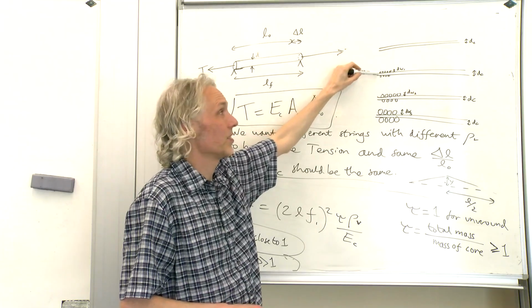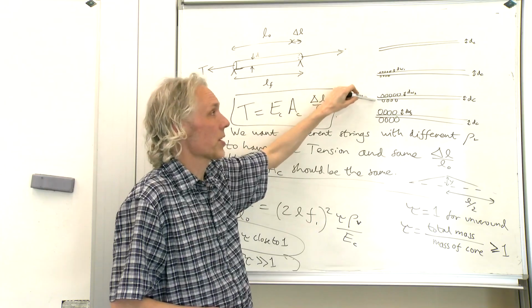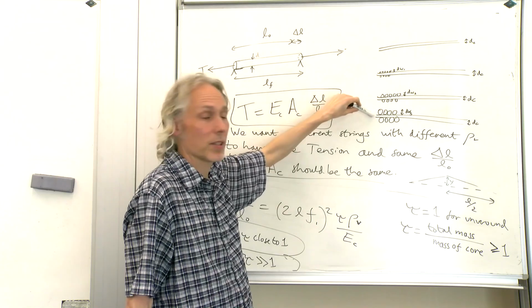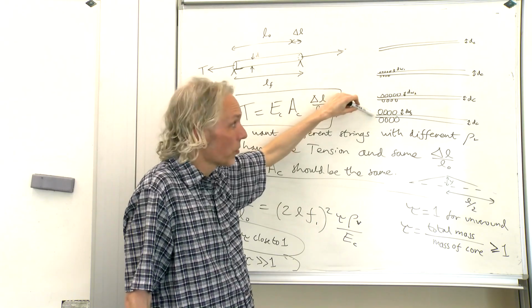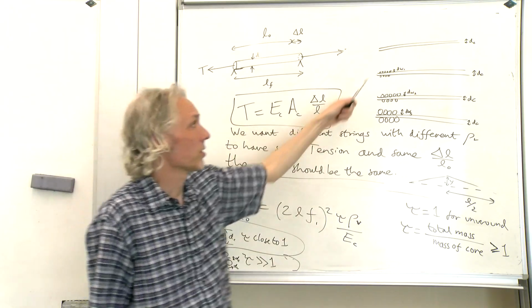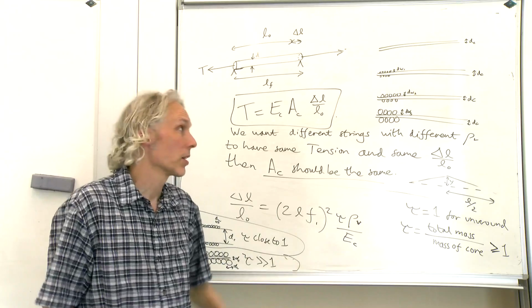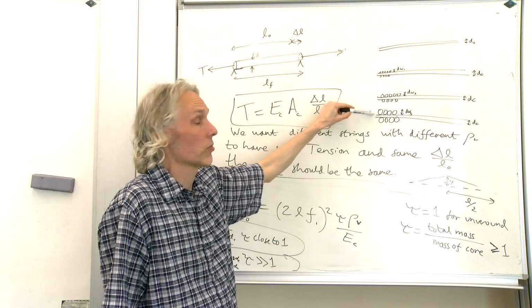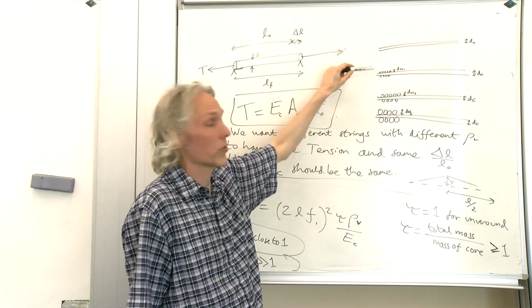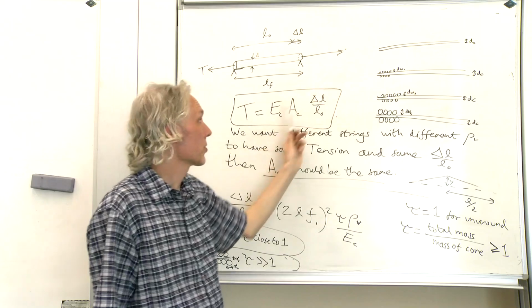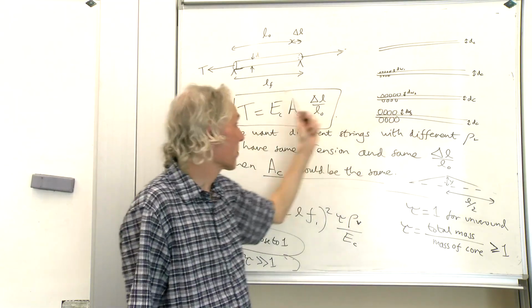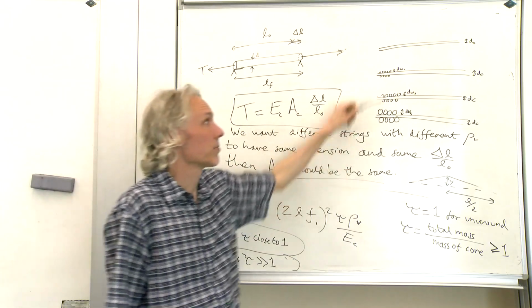And then this DC for this hex core is the same exact number as the DC, the core width for the A string, which is the same exact number as the core width for the low E string. So that means that if I design the windings right, to have thicker windings for the low E, thinner windings for the A, and finer windings for the D, we can get the tensions the same, and if you get the tensions the same and the core size the same, the engineering strain has to end up the same for these 4 strings.